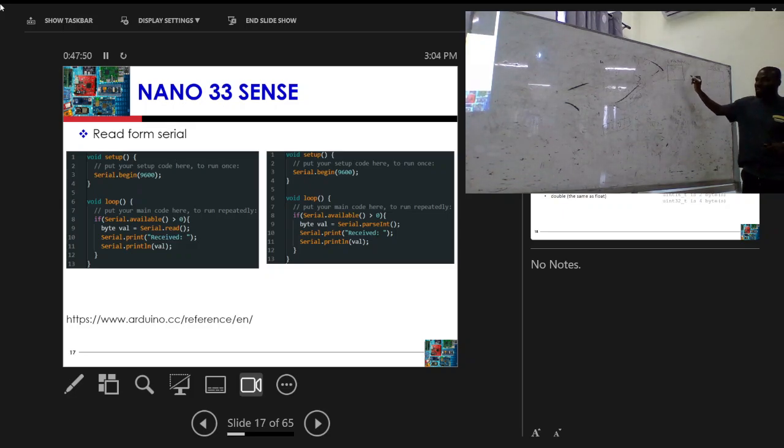The UART is a kind of two-wire way of sending data to and from two devices. So it means that we are using only two wires, right? Only two wires. There is one wire here known as TX. If I want to send data from the PC to the Arduino board, there's a port known as TX. That's where I'll transmit my data through, right?